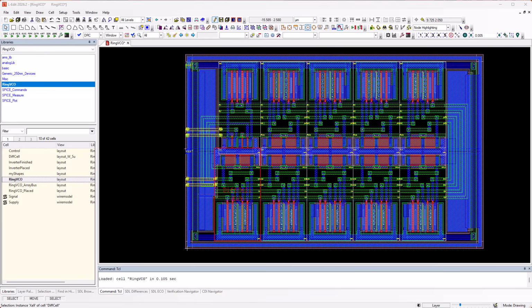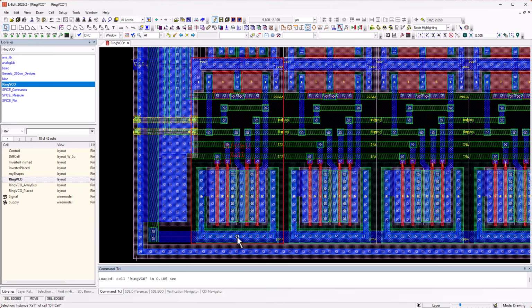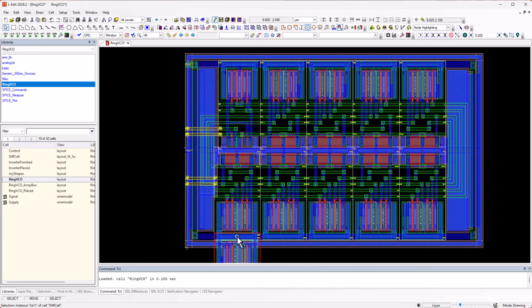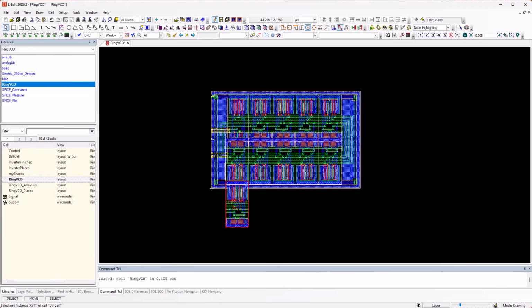Likewise, symmetry is fundamental in analog design. Traditional mirror operations often require additional positioning after the transformation. Basepoint allows designers to define the mirror reference directly. You duplicate the object, set a Basepoint, and then do a vertical flip, and you've just mirrored your object. So you choose the axis, perform the operation, and create symmetric structures with fewer steps.